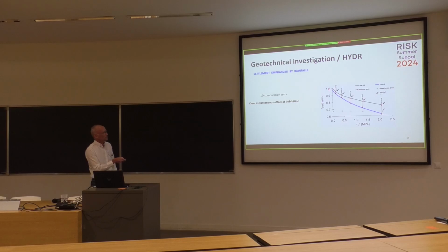In black, you have the compressibility of the rockfill in dry conditions. In blue, the same, but for the saturated condition. So the behavior is quite different. And then what we did, we prepared specimens in dry condition, and at a certain point, we flooded the specimen.